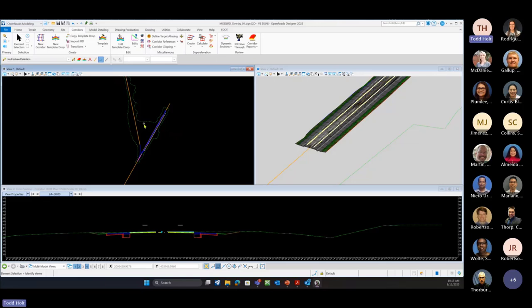And then in that complex terrain model, we can use the delta terrain to exchange out additional survey information. So if we had another terrain model that came in, we could edit the complex terrain model that's made up of our existing ground and a delta terrain. So those 2, the existing ground and the delta terrain, make up our complex terrain model of Wakulla.